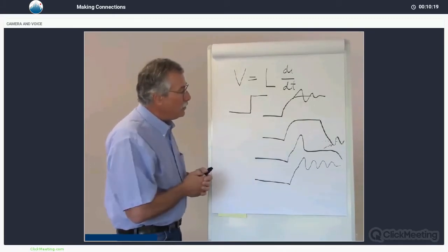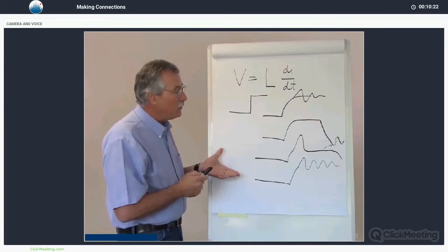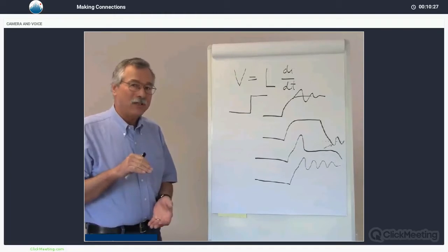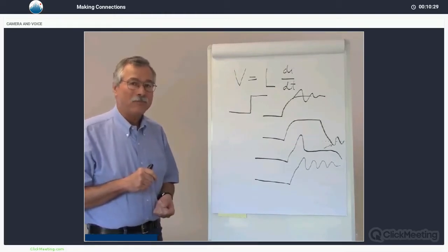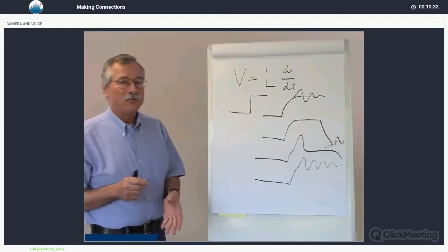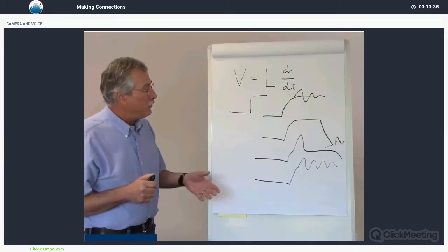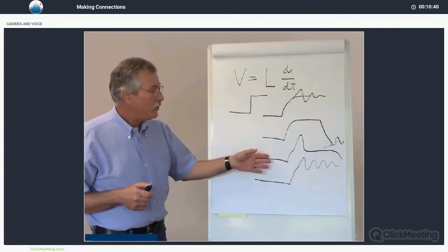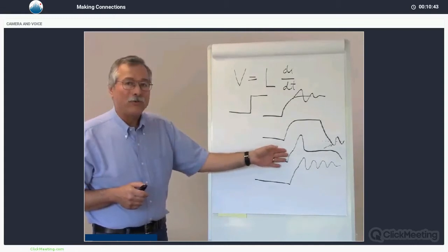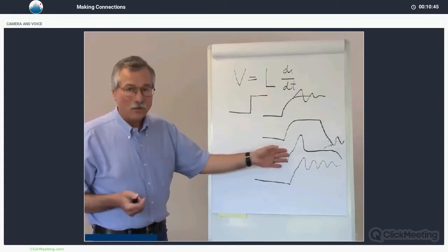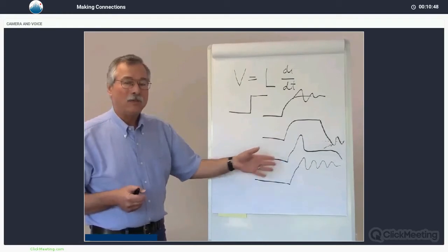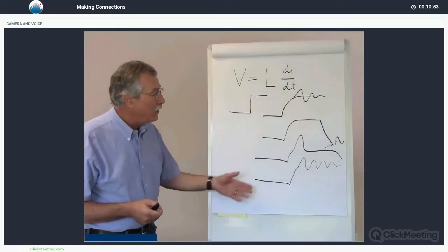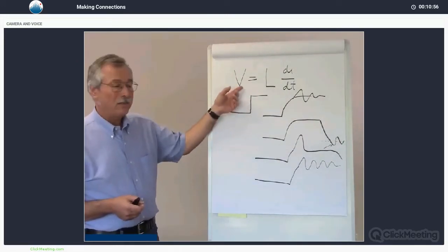There is one other issue that we have to deal with when we think about this, and that is a current source, like a laser diode driver, has a finite amount of voltage that it can generate. That's called compliance voltage. It's a current source, but the voltage is used to drive the current through the load. And if it turns out that we have a lot of inductance in our system, we may run out of compliance voltage and not even be able to reproduce the pulse, which is why Steve mentioned no pulse or low pulse. We have a lot of things to overcome: the forward voltage drop in the laser diode, the resistance in the connections, and the reverse EMF caused by the inductance.